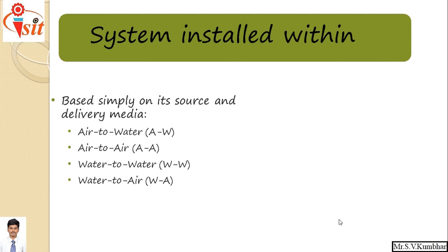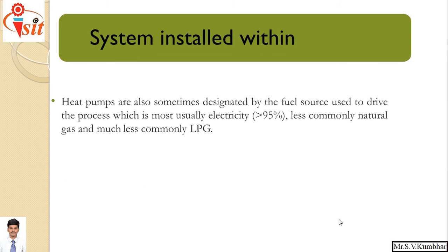So based simply on its source and delivery medium, these are the different types of heat pump: air to water, air to air, water to water, water to air, depending upon the heat transfer medium. So heat pumps are also sometimes designated by the fuel source used to drive the process within, which is almost always electricity, that is greater than 95%, less commonly natural gas and much less commonly LPG.